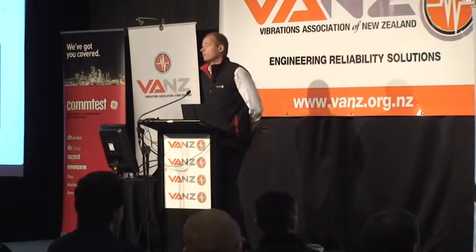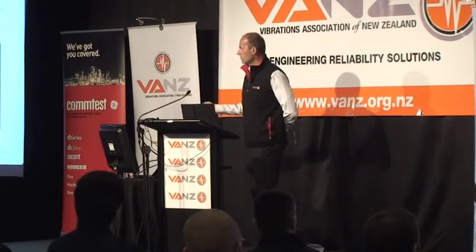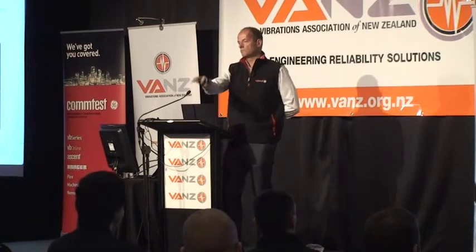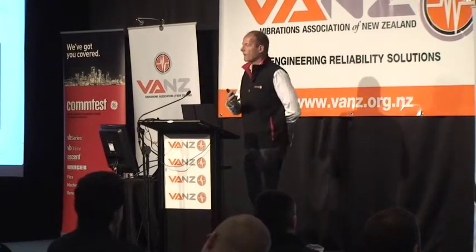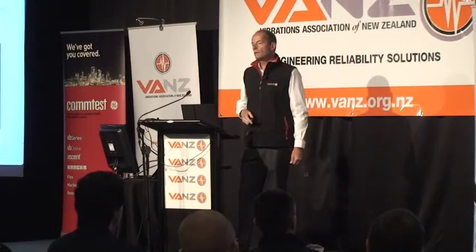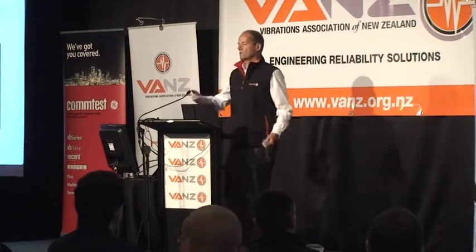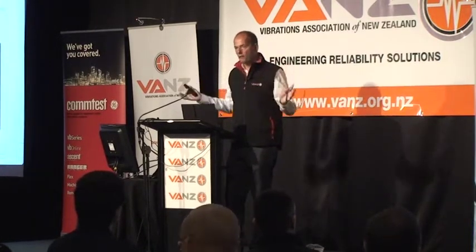Ultrasound is another terrific tool. We can use ultrasound to detect a lot of mechanical issues with the machine. We can check if the bearing's greased correctly. We can use it while we're greasing, which I'll mention in a moment. But you can use it for electrical applications. We can use it to check for leaks and a wide range of applications.